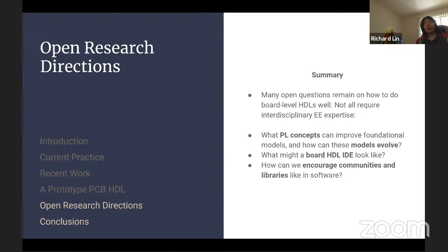So one piece of feedback there was that this is much stricter than current tools. So current tools, everything is a wire. It, for the most part, doesn't understand what types of wire it is, minus a very coarse type system. And one thing participants wanted, or at least one participant wanted, was just the ability to connect two things. So it turns out that modeling components in appropriate detail is time consuming. And sometimes it's just like, I want these two things to connect so I can get to my board. I want to put off the typing until later. So this could be an argument for gradual types. But overall, it definitely helps prevent errors, but it does require a bit more effort.